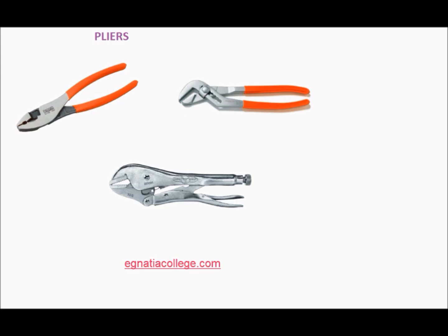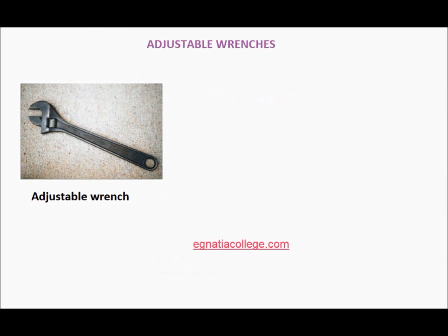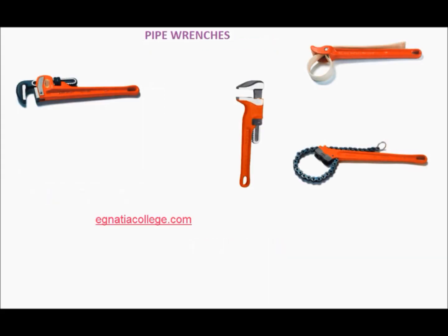Adjustable wrenches. Adjustable wrenches are available in various sizes, some with a cushion grip. The jaw opening is adjustable and smooth so that it does not damage metal finishes. An adjustable wrench is a great asset in any toolbox. Its adjustment range usually allows it to replace numerous open-end wrenches and sockets. Its compact design is useful while working in a tight space, such as working on water supply connections under a sink.